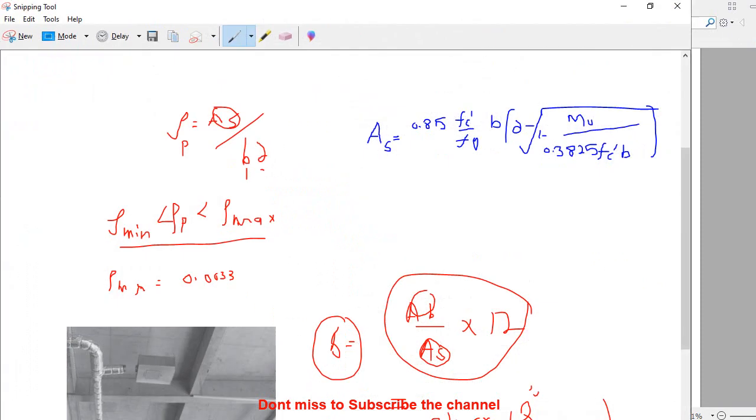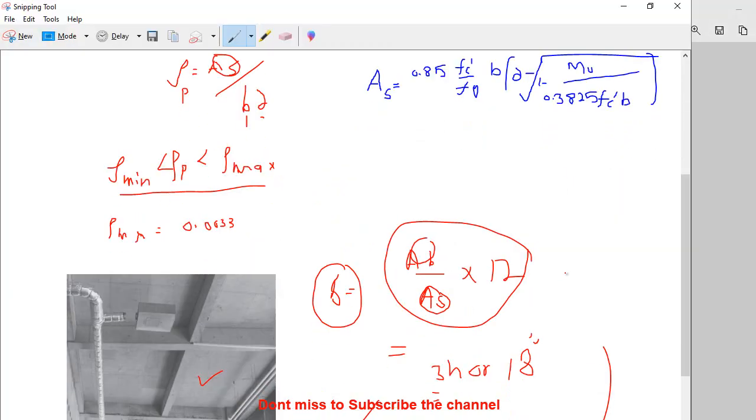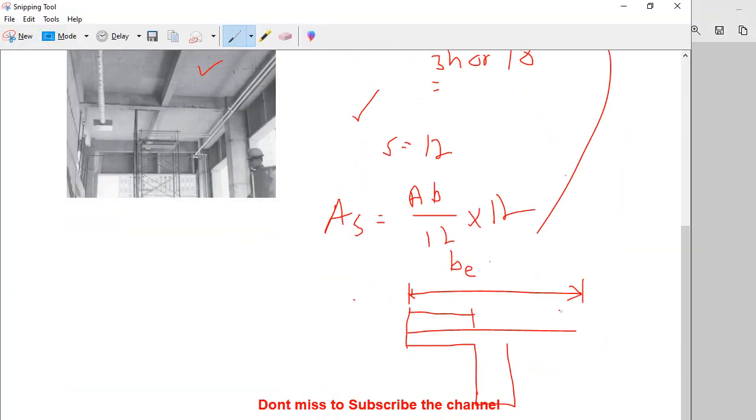Remember, here we have a cantilever portion, because in that girder, you see, here we have a cantilever slab portion. And the maximum moment in this case is wu ln squared divided by 2. This is the cantilever.